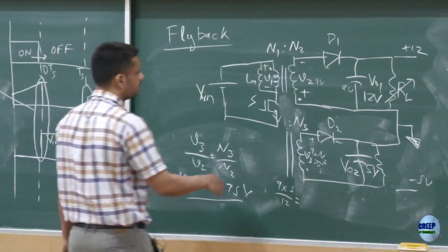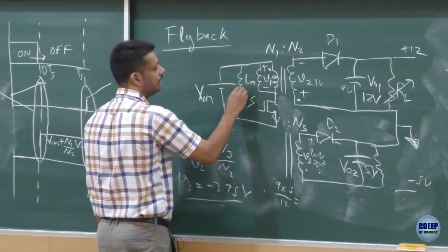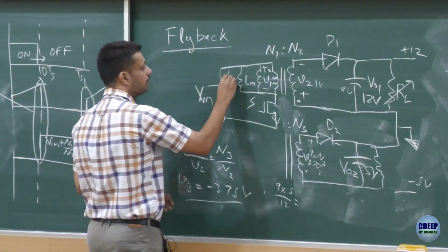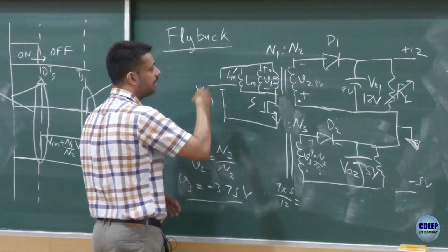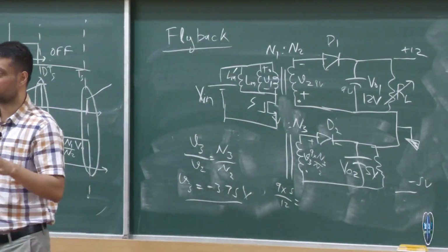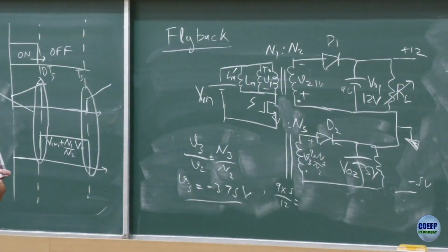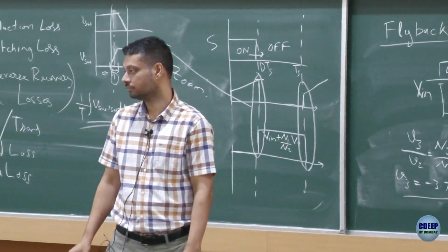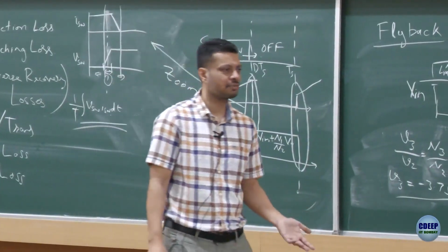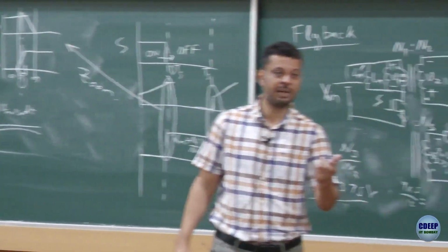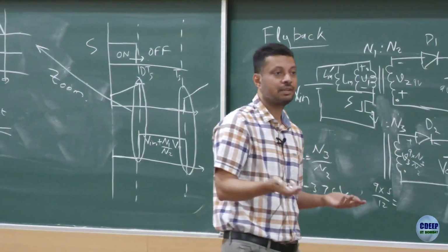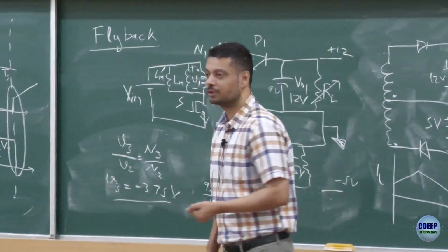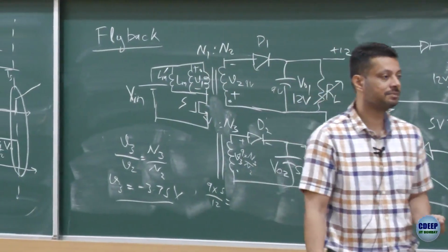Could add an extra inductor, okay, so let this Lm be there. I will take a core, put a few turns, make one more Lm prime, and add it with the transformer, and that should be able to overcome the problem we just talked about, right? Because now you are not using only the inherent transformer inductance, though it is also contributing a little bit; you can add an external inductor and design it to be the value you want, right? So unfortunately nothing bad with the circuit then.